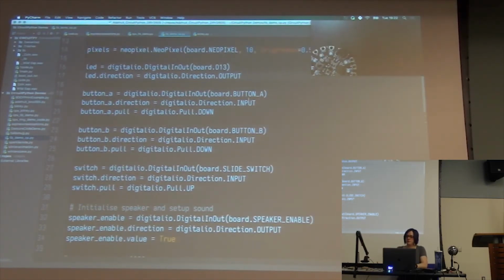So as an A to D, it's 8-bit, 0 to 5 volt, 0 to 3 volt? Well, the USB is 5, and this has 2 3.3 volt outputs as well as 5. Most of the stuff that's available can handle both. A lot of the LEDs want the higher end, but a lot of sensors are set up to handle both 3 and 5, depending on whether you're running it off a li-poly battery, which would be 3, or off USB, which would be 5. There's level shifters included in a lot of things so that you're not blowing anything out.